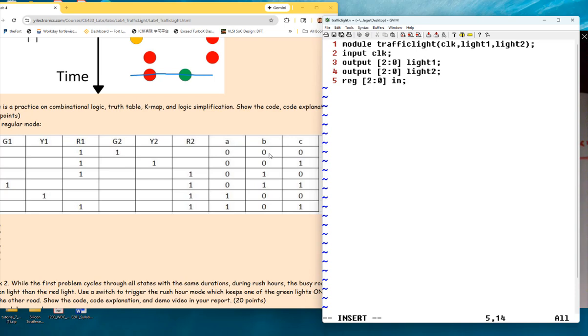We can assign an initial value to it. For example, it's a 3-digit binary number. Just give a 0 to it at the very beginning, so it starts from 0. Actually, we should, right? But by default, Verilog will directly give it 0 if you don't assign an initial value to it. It's a 3-bit binary number, and the initial value should be 0.